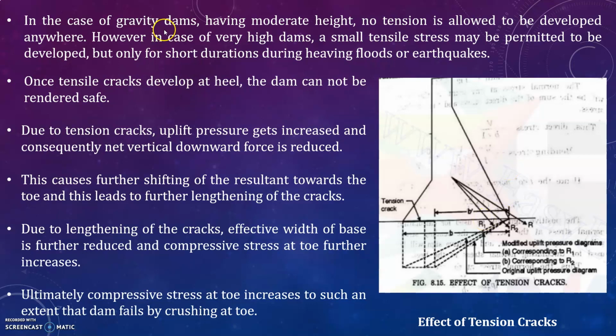In the case of gravity dams having moderate height, no tension is allowed to be developed anywhere. However, in case of very high dams, a small tensile stress may be permitted, but only for short durations during heavy floods or earthquakes.